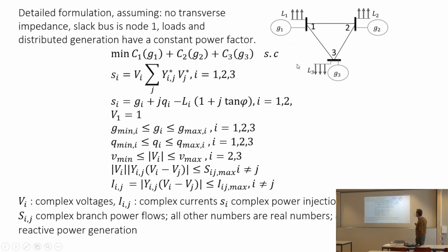In such a grid, usually one or several of the buses have to be swing buses. They have to be the buses that will provide the instantaneous balance of power, also called the slack bus. In a distribution grid, this is typically the point where a transformer connects you to the main grid.